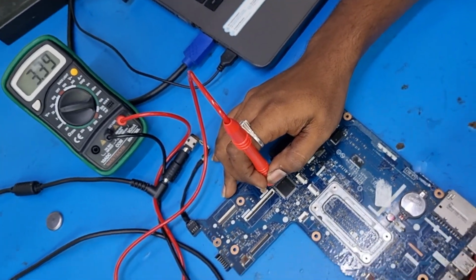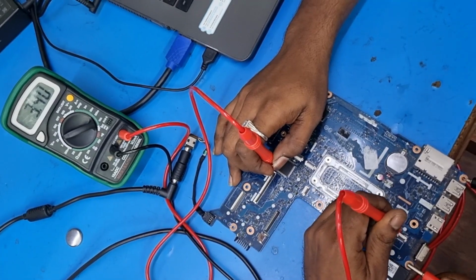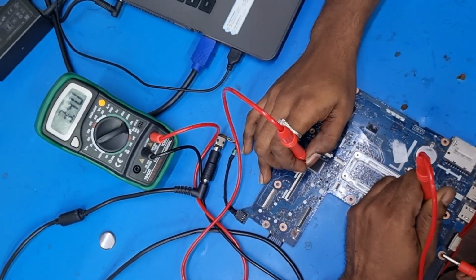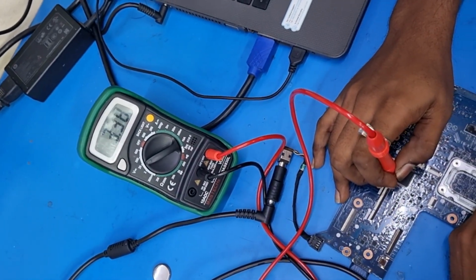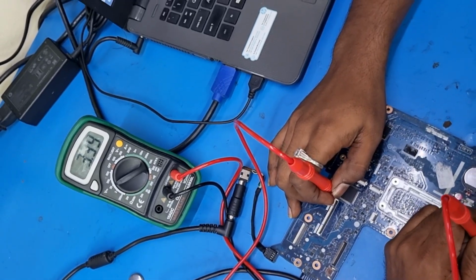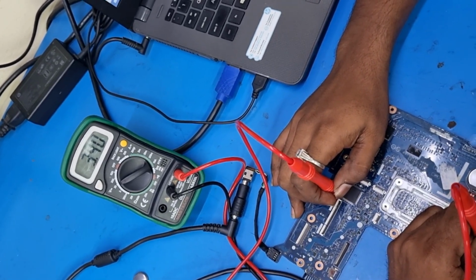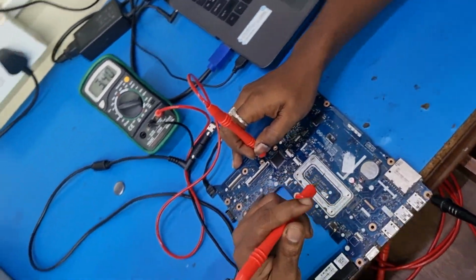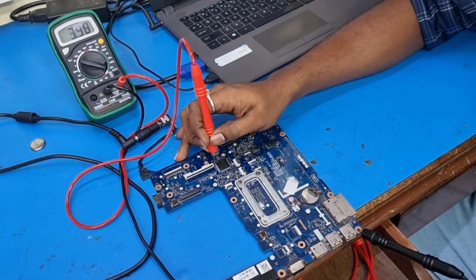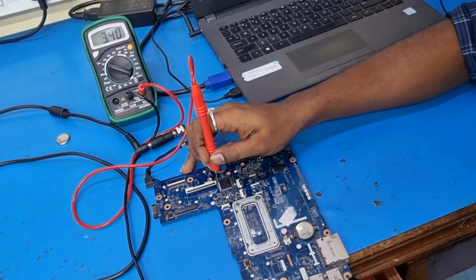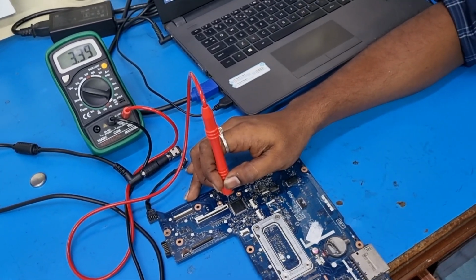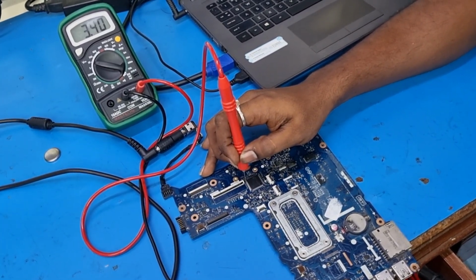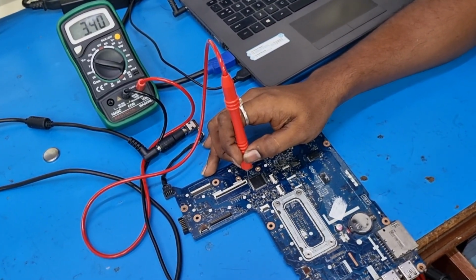So we'll see practically here. We connect, 3 volt is showing at PM power button pin number 4. We press the power button, it goes to 0, and when we release the power button, it comes back to 3. You can see here a pulse is coming. We'll see once again. Yes, see 0 and then 3. So in this way this pulse should appear. Otherwise, if such a change does not appear on the multimeter, then in that case our SIO may be bad or EC bias may be bad. So we have to conclude like that.